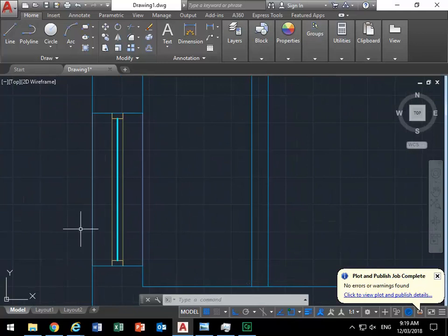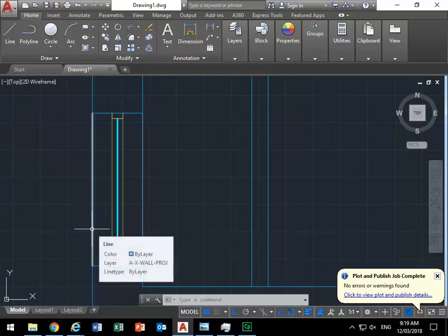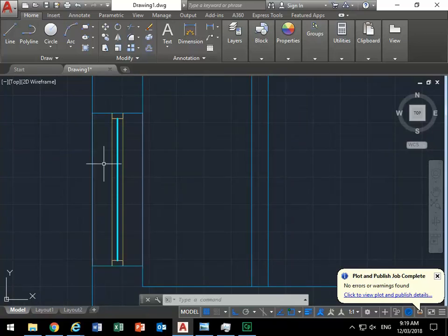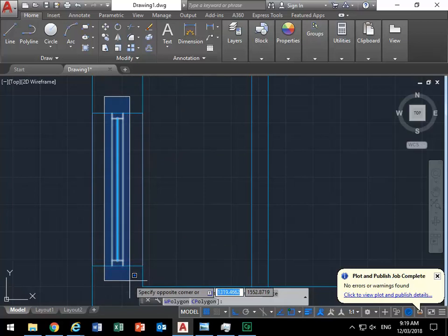And anything that's repeated like this, the basic rule is if it's repeated more than once, you should make a block for it. And you should be able to make your own blocks. If you're relying on blocks from the library, you're never going to get there with AutoCAD. You'll see any experienced person with AutoCAD won't really use other people's libraries. They'll make their own. And again, they'll make blocks as they go, like I'm doing now.